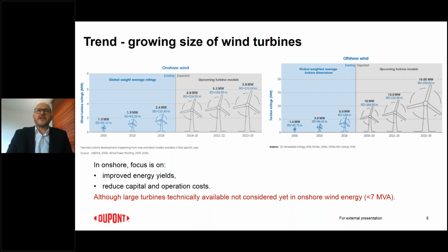So that's why the offshore industry really appreciates the availability of the largest turbines available, and then the largest turbine developments. At the moment, we have the turbines in the range of 12 megawatt with the transformers of around 14, 15 MVA. So these are the small power transformers already, not distribution transformers anymore. So these large turbines are under development.